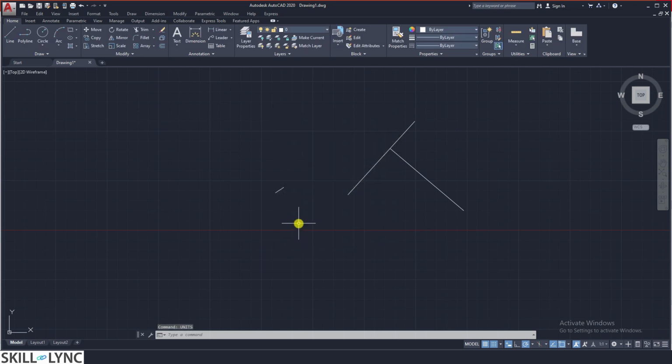Now this pretty much sums up the basics, looking at the lay of the land. How about navigating the tools available in AutoCAD to suit your requirements? Next, let's look into two frequently used commands for navigating through the commands, that is undo and redo. If you recollect, we were using the oops command to undo any mistaken erasing.